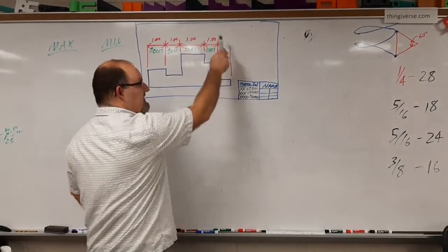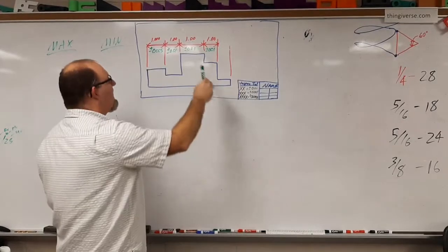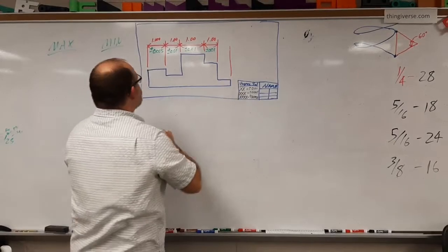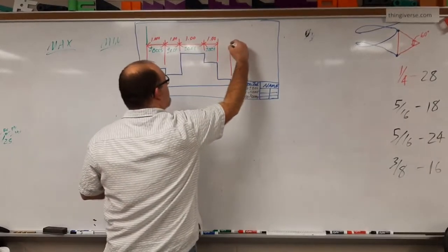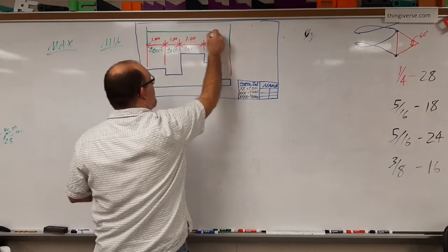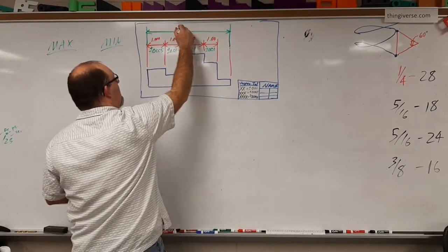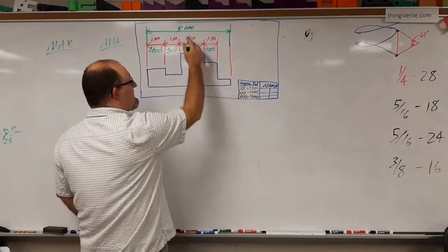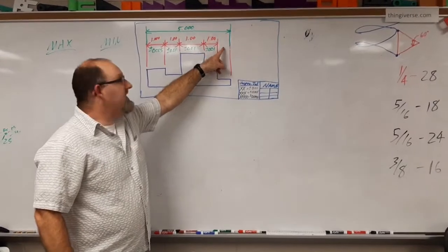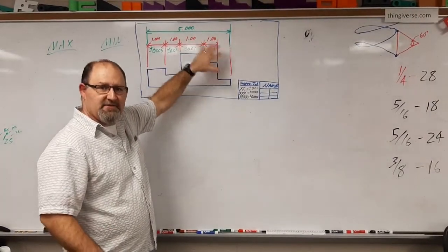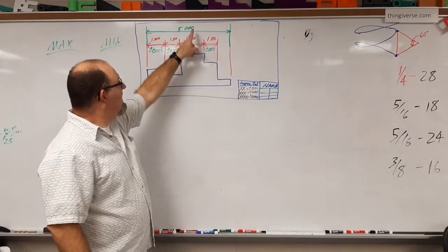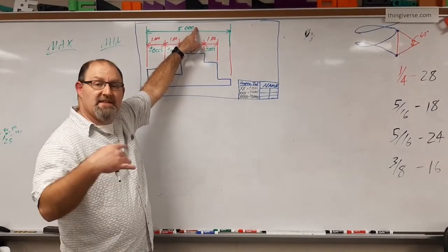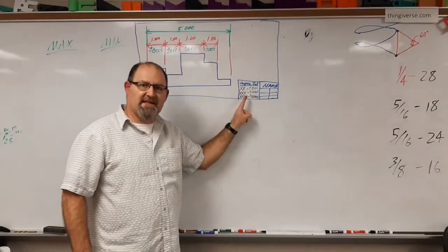I erased off the reference dimension from the chain dimension video. And now we're going to let this area right here become the runout. In this case, this will now be a controlling dimension, 5.000. Okay? This one was a 3-place decimal, and we'll put this one at a 3-place decimal so you can see some of the differences here. So now instead of it being a reference dimension, this is an actual dimension. This dimension is now controlled by the unspecified tolerance block.